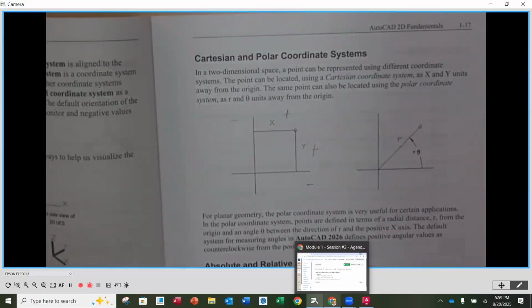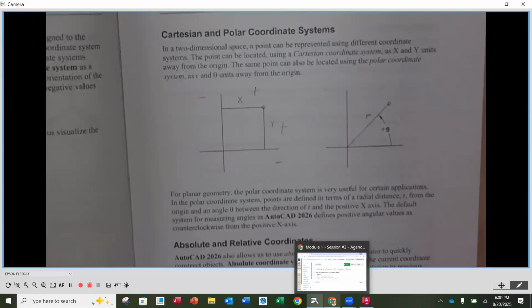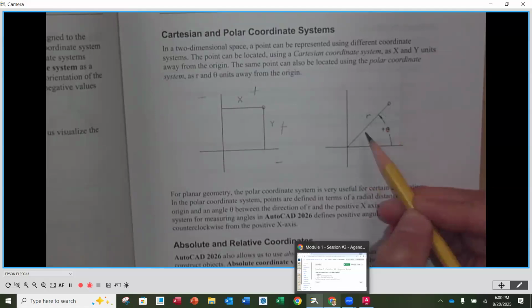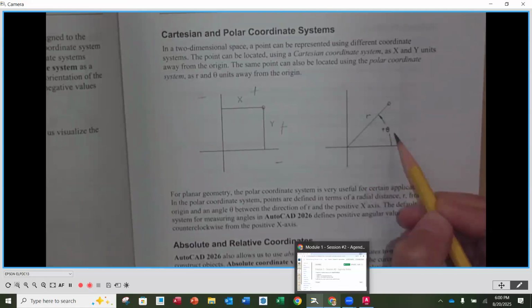We have to put a minus in front. Okay. Familiar math, other applications of X, Y coordinates, right? Now, again, we're not worrying about Z. The other type of input that we can put in is what we call polar coordinates. Polar coordinates are where we give it how long of a line, and then what is the angle that we're going to be going at.